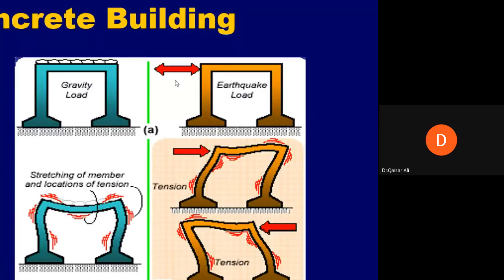It is possible that the full live load does not exist at that instant of time, but the full dead load or superimposed dead load would be there when the building is being hit by an earthquake.